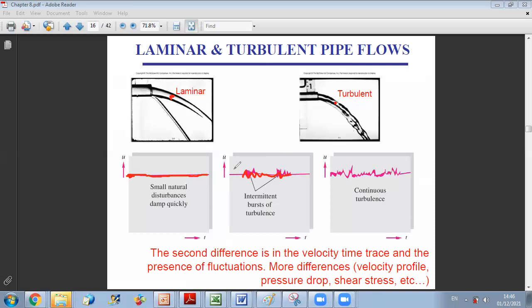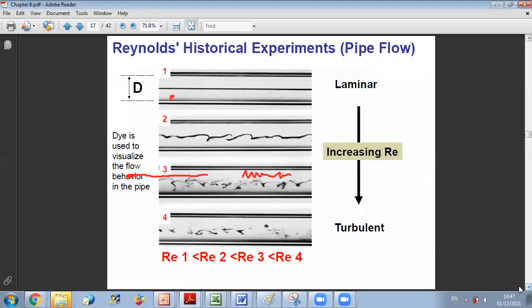This will make analysis much more complex, okay? So we have then to account for the turbulence effect, which is really complex to solve, and we cannot find it analytically, so we should go to experiments or computational fluid dynamics. And as the Reynolds number increases, the mixing behavior increases, and the turbulence level will increase.